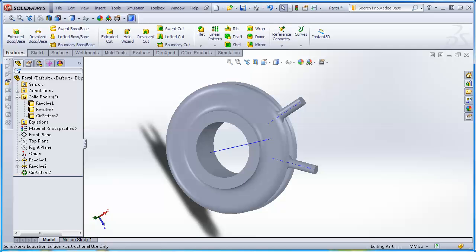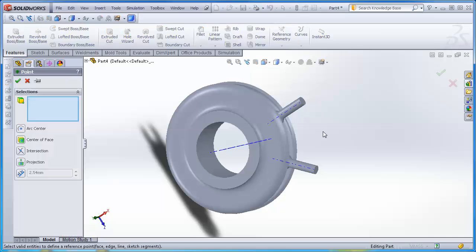I just paused for a moment because I got interrupted in my office, but I am back now. To make the sweep, I've already planned and thought ahead on the sweep and know some complications where I can make some things easier. One way is knowing where my sketch is going to go for the sweep that connects these 2. I'd like to have a point at each edge of the sweep to be able to grab later. So I'm going to create reference geometry, a point, on the arc center of that arc, and accept that point.